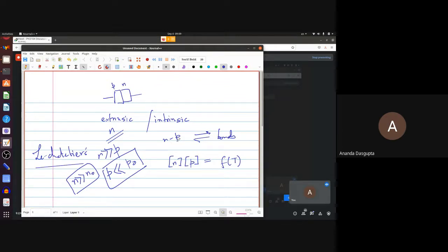Or it will function in a way which will be very detrimental to the way your circuit works. Okay. Usually, when people rate something as a safe current, there is always a margin of error. It means, suppose somebody says 1 ampere is a safe current through this diode, it doesn't really mean that it's going to burn up when you exceed 1 ampere. It actually means that it can really withstand more than 1 ampere, but just to be on the safe side, don't give it more than 1 ampere. Almost always these ratings are made on the conservative side. You try to be safe.